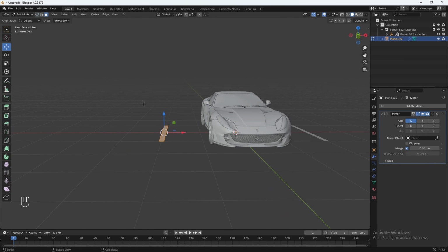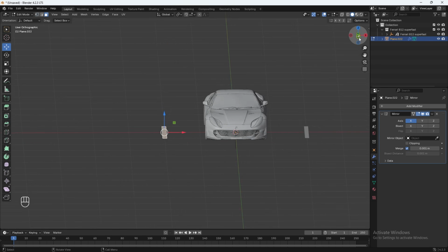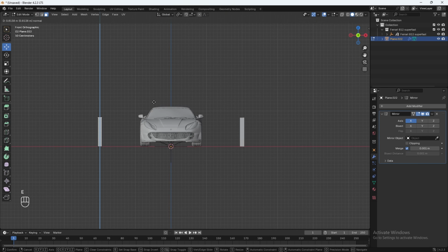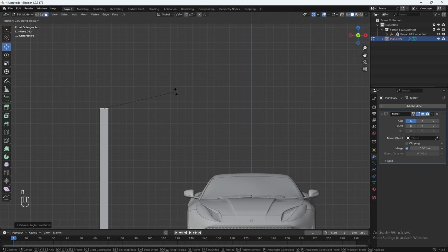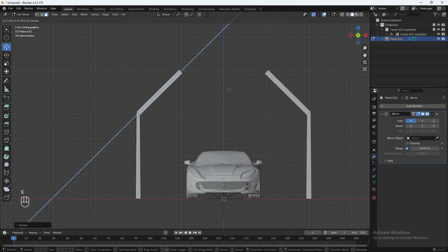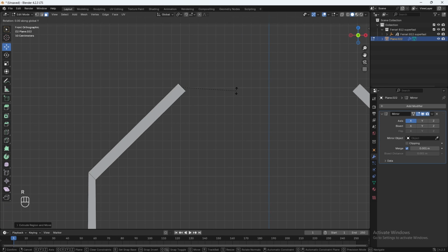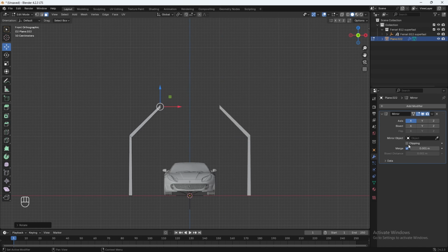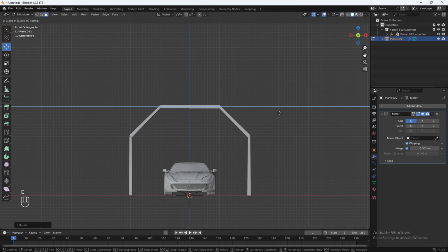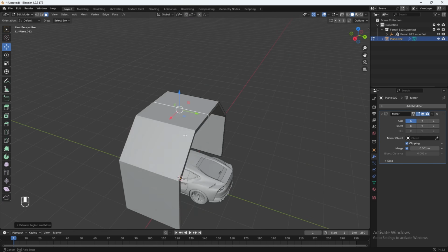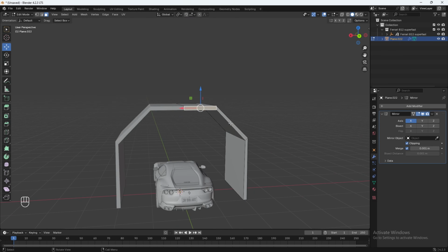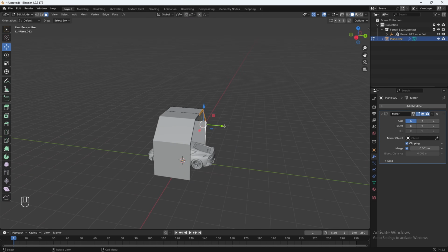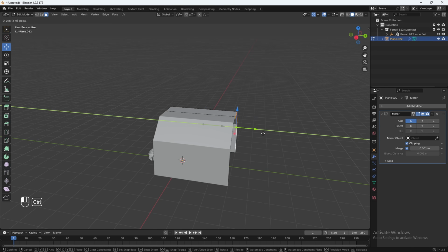Now go to your face select, select your top face, go to -Y, hit E to extrude up, hit R, Y, let's rotate it. E again, let's extrude this way. R, Y again, straighten it out. Check mark this clipping tool, hit E, and then bring it to the middle. Click. Go to the back, select these faces by holding shift. Then you can drag back like this.